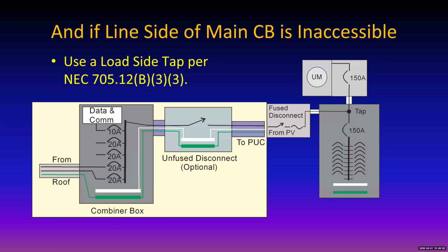Now, how can a silly little PV system overpower the utility? It's very simple. It's the voltage. The PV system simply operates at a voltage simply high enough to make sure that the current always comes out of it. And it ends up at a voltage equal to whatever is there at that tap condition. And that voltage is less than the voltage that the utility is trying to use to send it through to meet the needs of the load. So it's a thing that adjusts itself automatically.